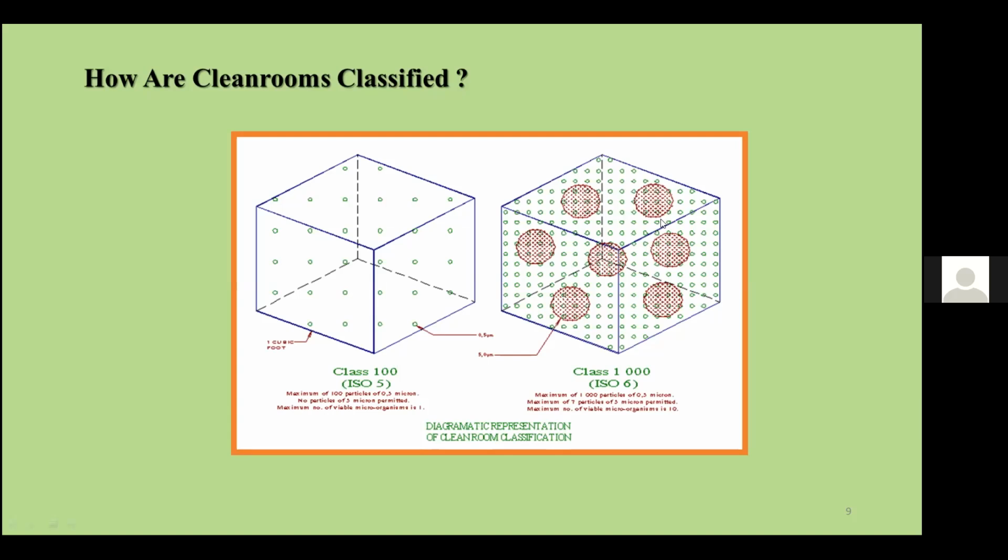So what is the difference in this classification? Wafer fabrication is a very sensitive thing, so it is only done in a class 100 clean room. We cannot do it in an open environment, because silicon chip fabrication is very sensitive to the atmosphere.